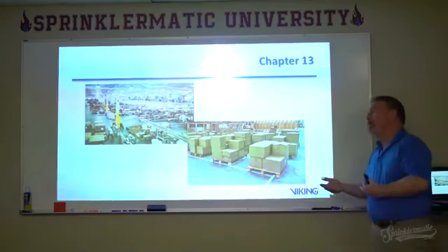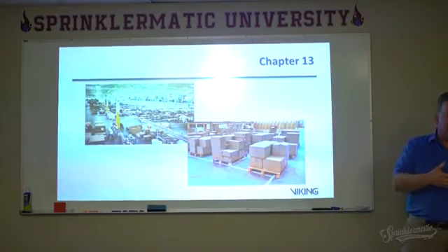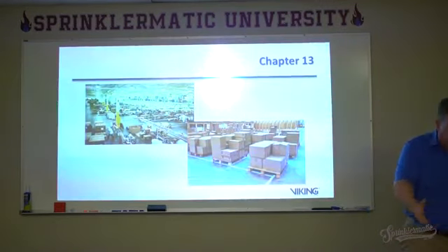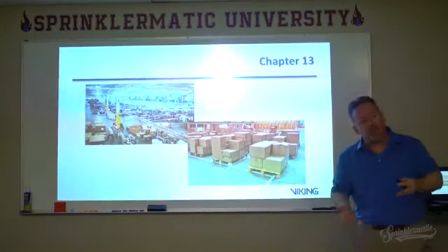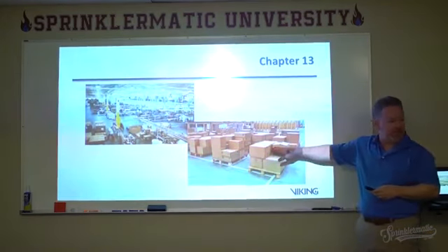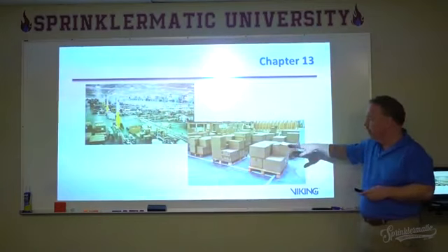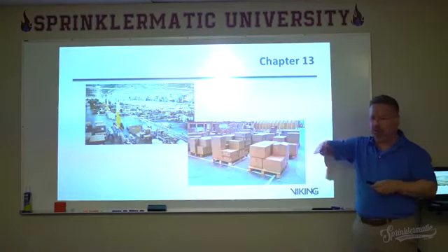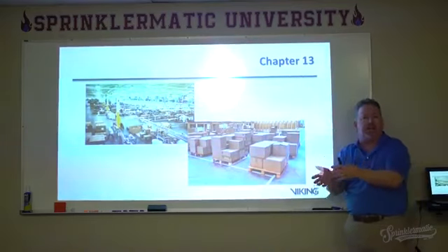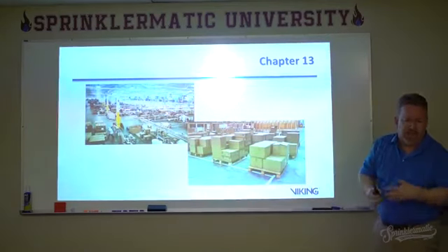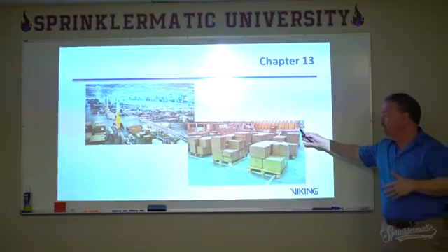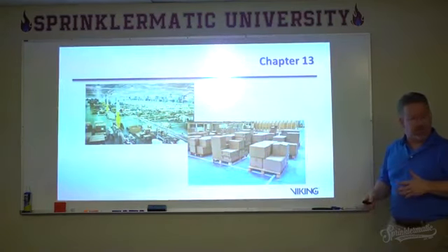So what it becomes is what over the past editions was called miscellaneous storage, and it was kind of limited to this one particular area, and we'll talk a little bit about that in a moment. But now it's also got low piled storage. So this is a warehouse. It's not anything else. It's not anything that actually can be defined as an occupancy hazard classification per se, but it is a storage application. But it's low pile.